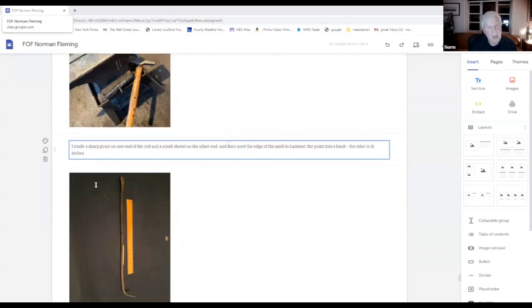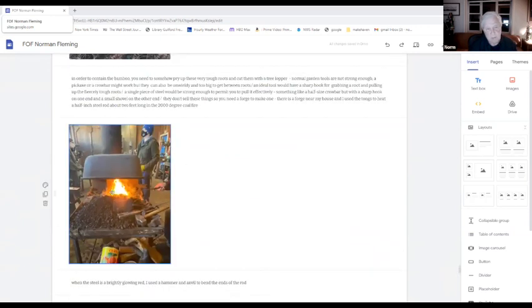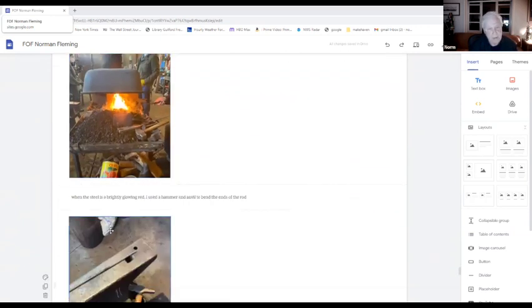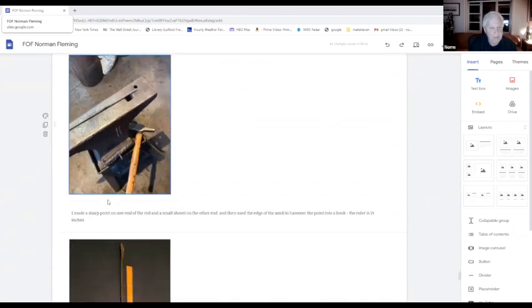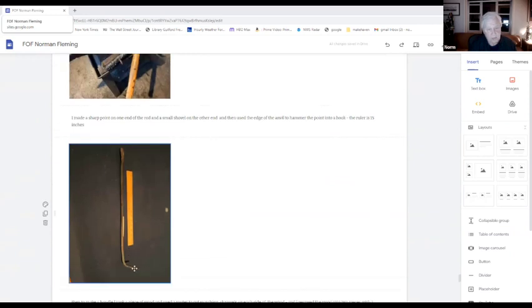Well, I took a quarter to half inch steel bar and heated it. It has to be glowing red hot, then hammered it down with a hammer on the anvil. If you hammer along the edge, you can sharpen one end, which I did, so that it'll pick down into the bamboo. And I wanted it at not a tremendously sharp angle, because then I would have a hard angle pulling it over.